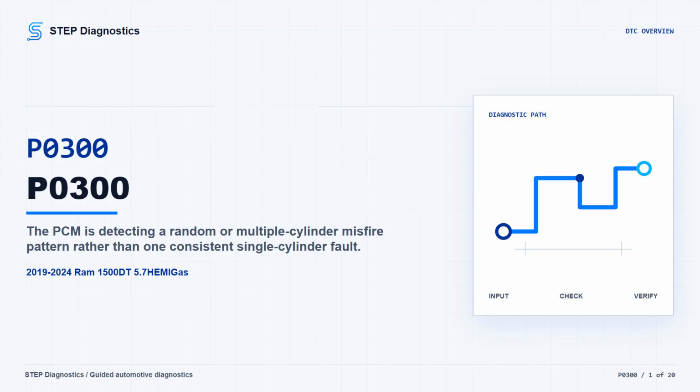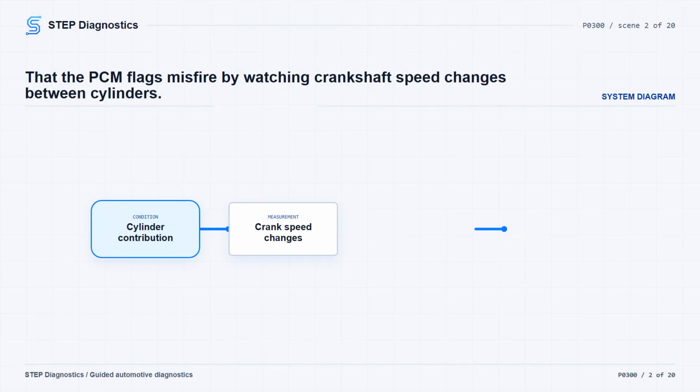The fault area can be fuel, spark, air flow, oiling and cam control, EGR leakage, carbon buildup, or an engine mechanical problem, so the key is to work the path in order and not guess. Start with the basic system checks first. The misfire monitor is a gate, not the fault itself.